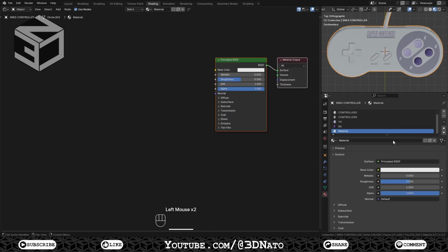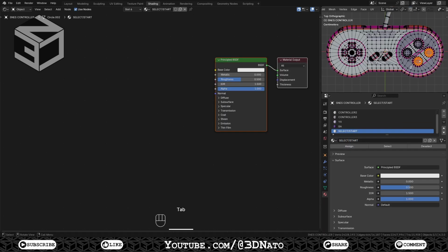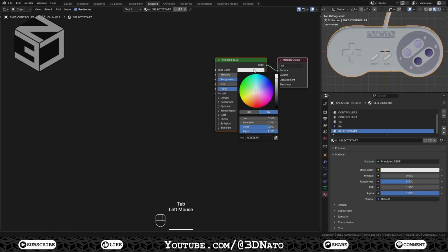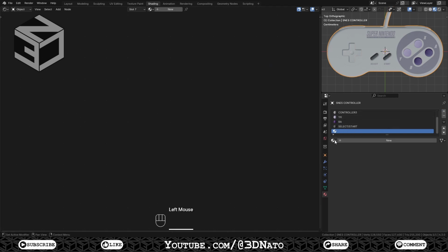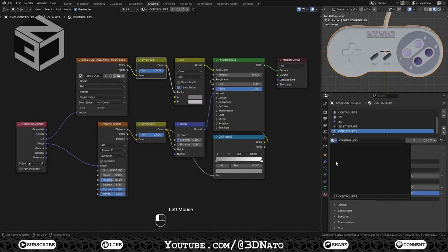Press the plus sign to add a new material and rename it Select Start. Go to Edit Mode, select both Select and Start button faces, click Assign, and exit Edit Mode. Set HSV hue to 0, saturation to 0, and value to 0.05 to make a dark gray color, and set roughness to 0.75.